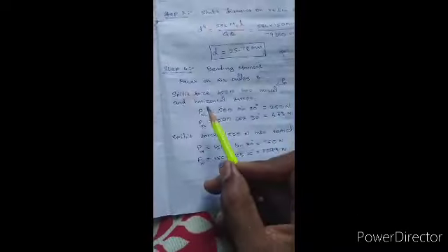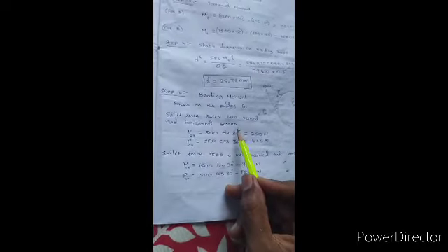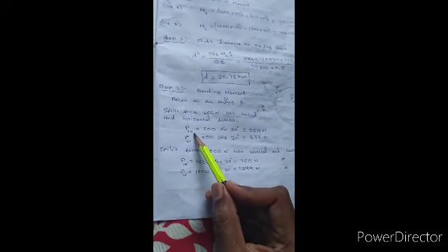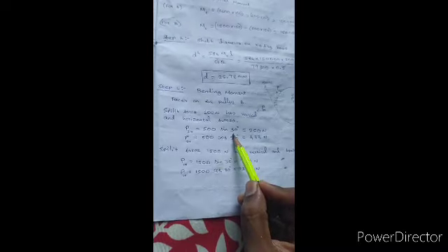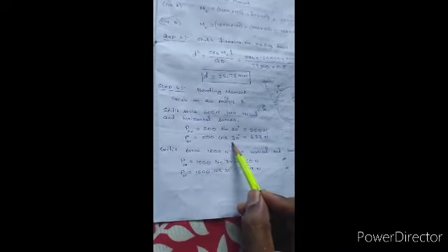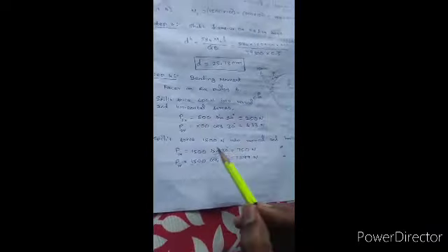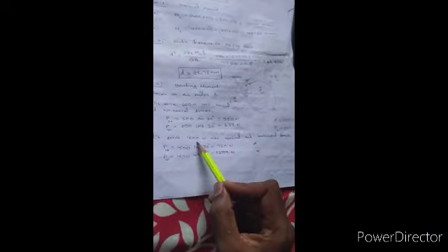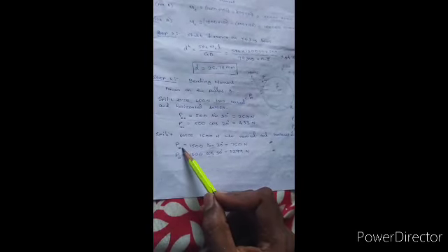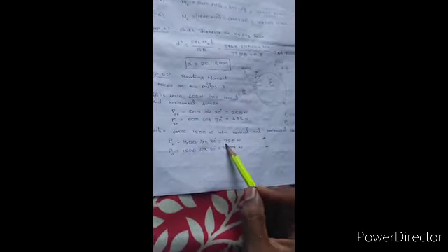Okay. So I have done it here. I am splitting the 500 Newton force into vertical and horizontal components. To make it into the horizontal component, multiply it with the sin 30. To make it into the vertical component, multiply with the cos 30. Okay, 250 Newton, 433 Newton. Similarly here also, the 1500 Newton force, split it into horizontal and vertical. To split it into the horizontal force, the value is 750. Vertical force, 1299. Okay, so now we have split the inclined force into horizontal and vertical.